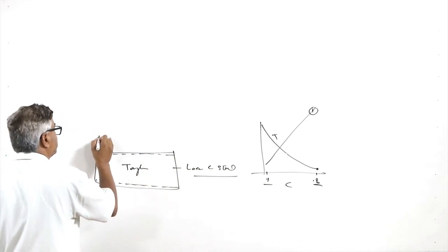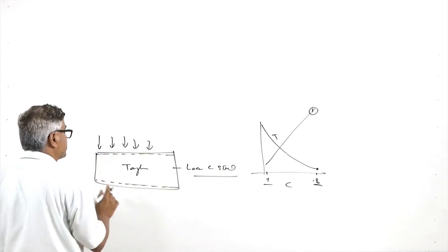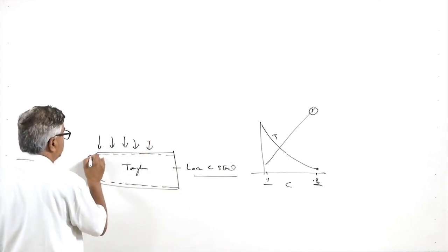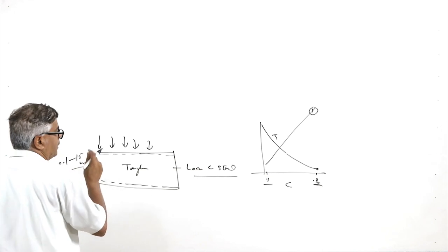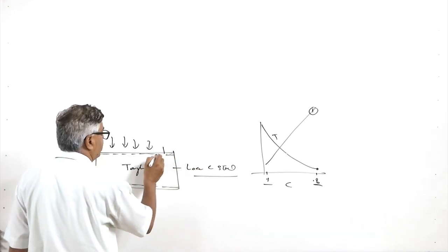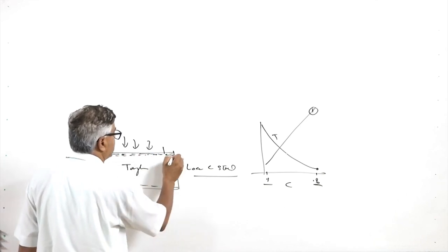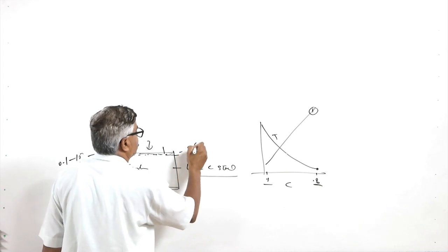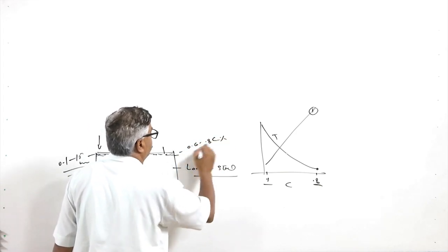For this purpose only, the carbon is introduced near the surface layers, and this can be introduced up to the depth of say 0.1 to 1.5 mm, depending upon the purpose for which it is to be introduced. So, once the carbon gets enriched near the surface layers, and this enrichment is done up to the point like say 0.6 to 0.8 weight percentage.